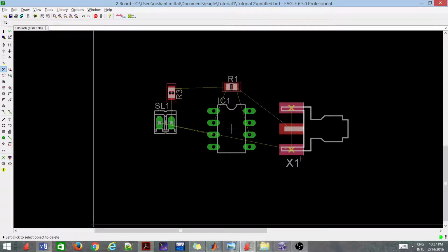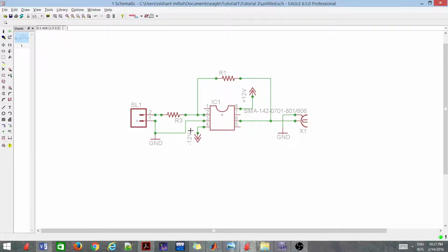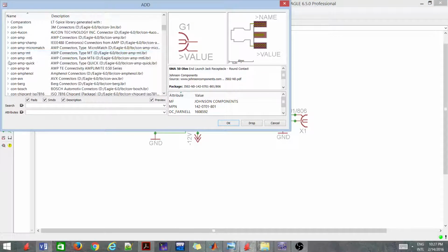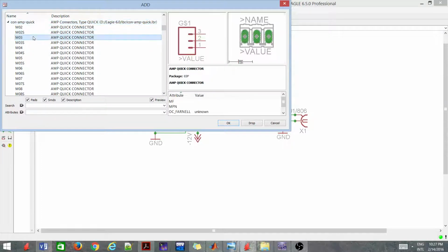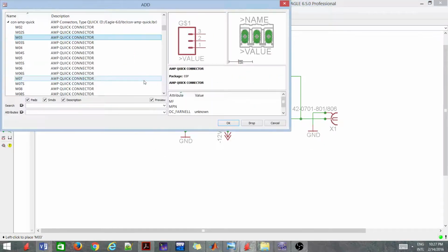Okay, so I think things are pretty much done now. Are all the connections as per the needs? Oh yeah, we missed the VDD ground. So this one would just create the nets. Okay, if you want to give a supply to the circuit, we would need further a connector which would be connected through the external power supply. So again I'll be going to this quick. So we will be needing a VDD, ground and a VEE.